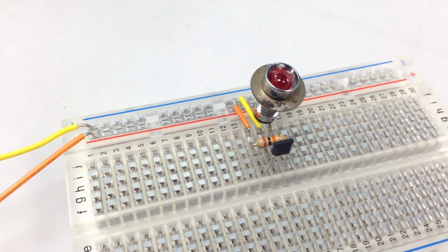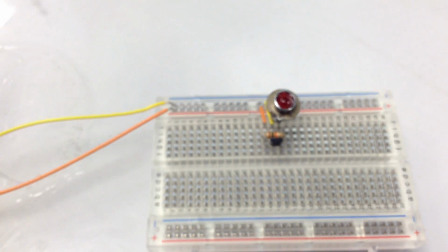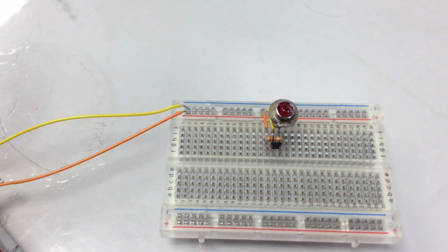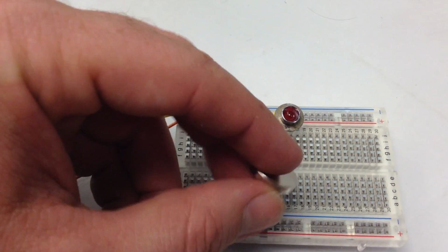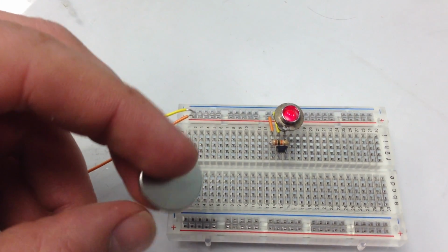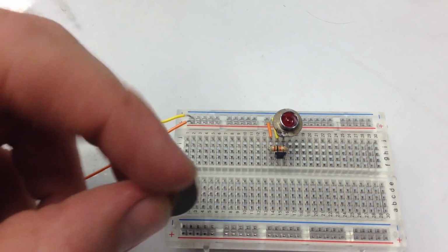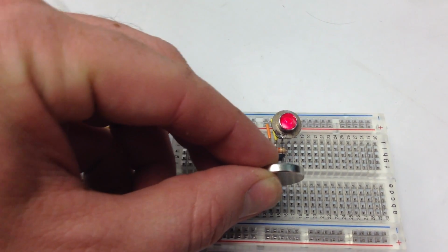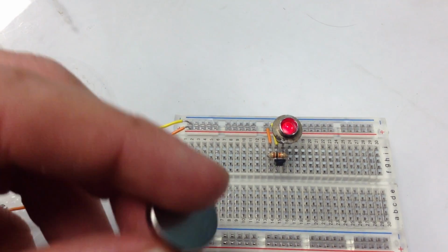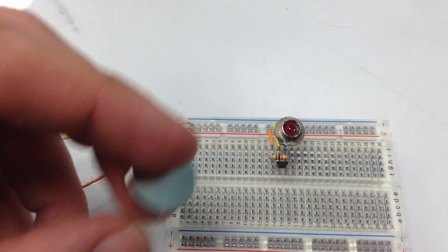As one side of the magnet passes next to the sensor, the LED turns on, representing the 5-volt signal. The light stays on, showing that it is a latching Hall effect sensor. To unlatch or turn off, it would require a magnet with opposite polarity to pass by, changing it to its low signal state.